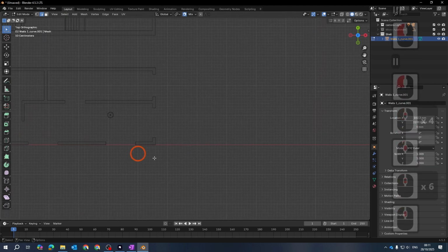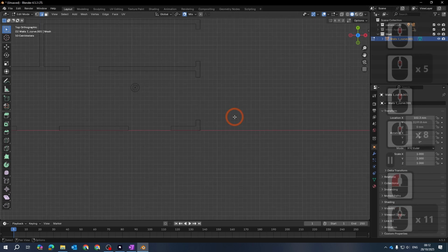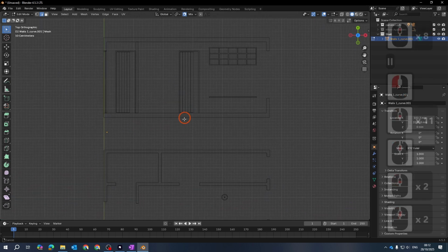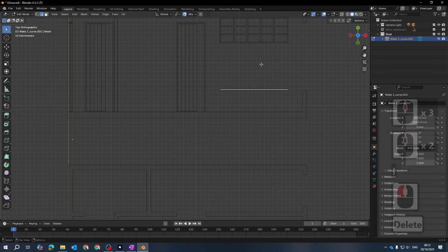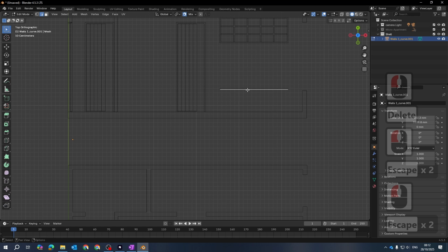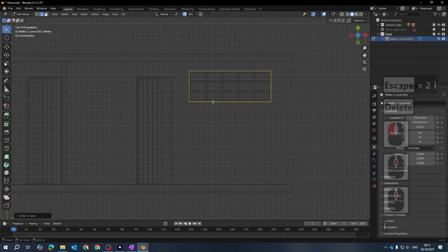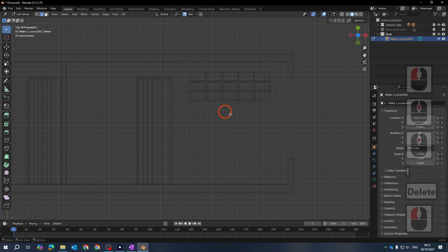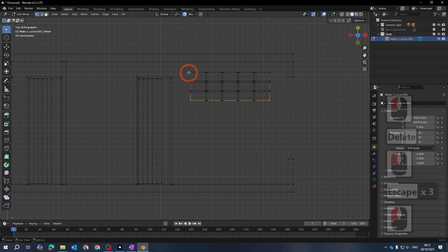So there's some holes in the geometry that we need to sort out as well. So if I go L, okay, so how do we fix that? I'm starting to get rid of some of the linked information that I don't need. So let's see, just hover again. So L, delete vertices. You want to delete the vertices. So go L again. Delete vertices, L again. So it'll try and find all the linked information. Alternatively, I can just go to vertex mode and I can simply select all the vertices and delete them.